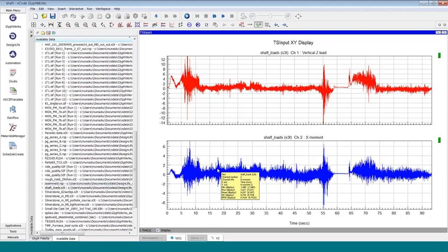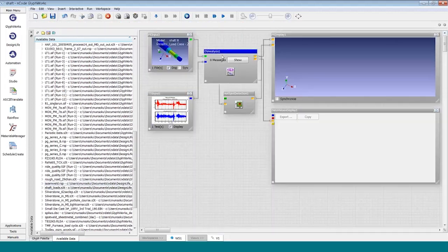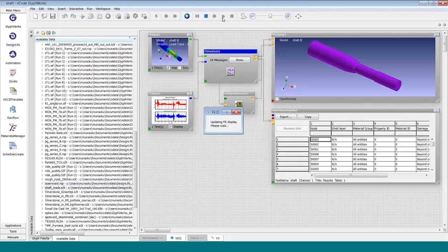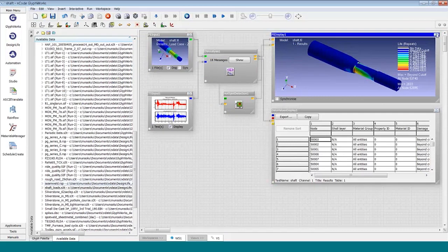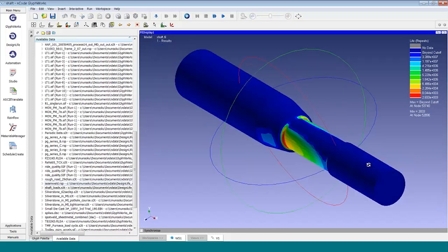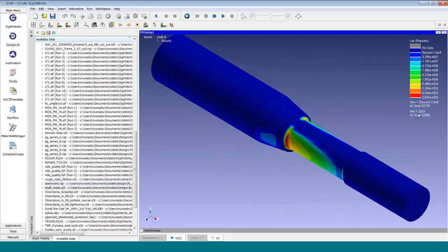it's got a material curve built into it and such. I'm just going to go ahead and run this. And you can see what we've done here is this plot now is a fatigue life contour plot that shows that the minimum, if that was 1 lap of the proving ground, then we're predicting about 2,800 laps to failure. So really, each and every node here acts as its own virtual strain gauge, you could say, and that way we can monitor hotspots in the whole model rather than just wherever the strain gauge was placed. So that is a really quick look at